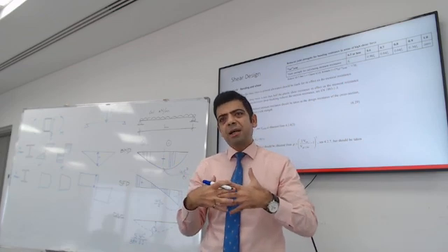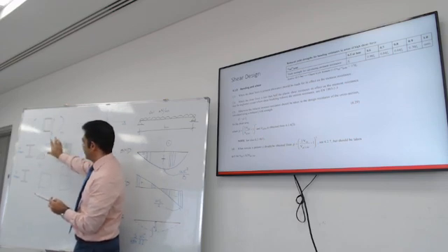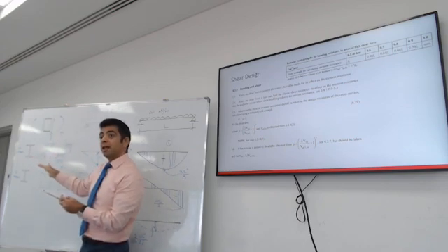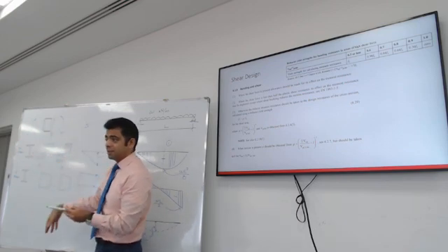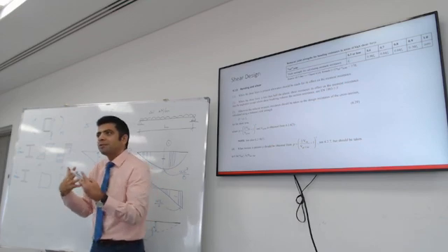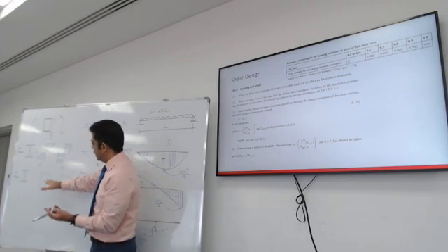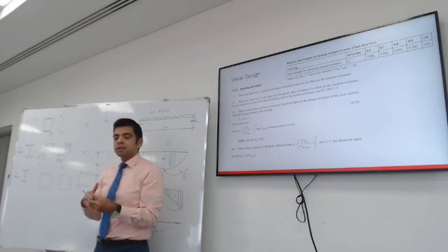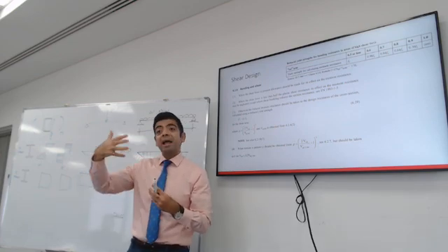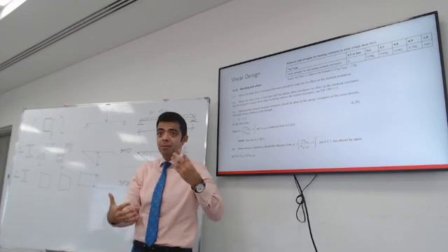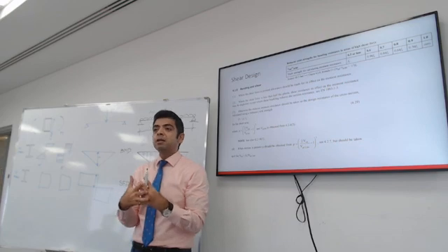You're overstressing the section. If you put too much bending, the top is approaching yield. If this is class 1, you can allow the section to develop yield on the entire section. So the section is exhausted, it's yielding. It has no more capacity. If you add to it a lot of shear, it's not going to be able to take both. It's not going to be able to take maximum plastic moment capacity and maximum shear resistance capacity. It's too much for the section.